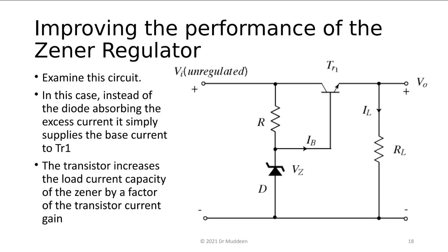Once you design a specification, that's the exact design. The only things you really can't change are the actual resistor values and so on. The things that bias the circuit, and the voltages and currents that make the circuit work, you can't change. But what you can change are the power ratings of the components, to make sure that they can handle what you're asking them to do.